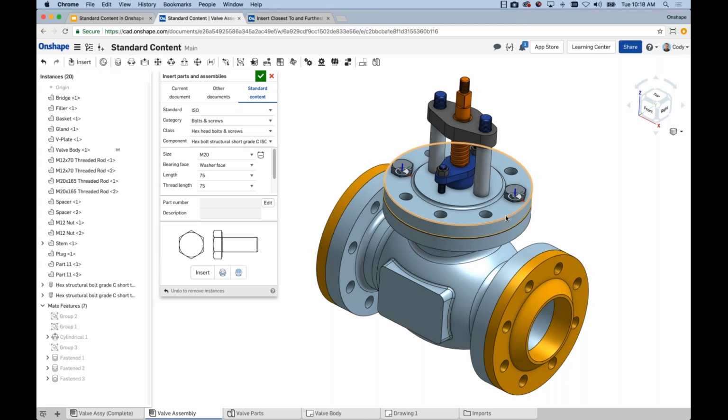One big thing that I would point out, and it's going to be something inevitably that you'll run into, is you can also undo as a step in the process, right? So I can click the undo arrow. Again, I've never closed the insert dialog. I'm just clicking undo, and it's going to undo inserting all of those bolts. So you don't have to exit the command. You don't have to exit undo and then go back to the command.